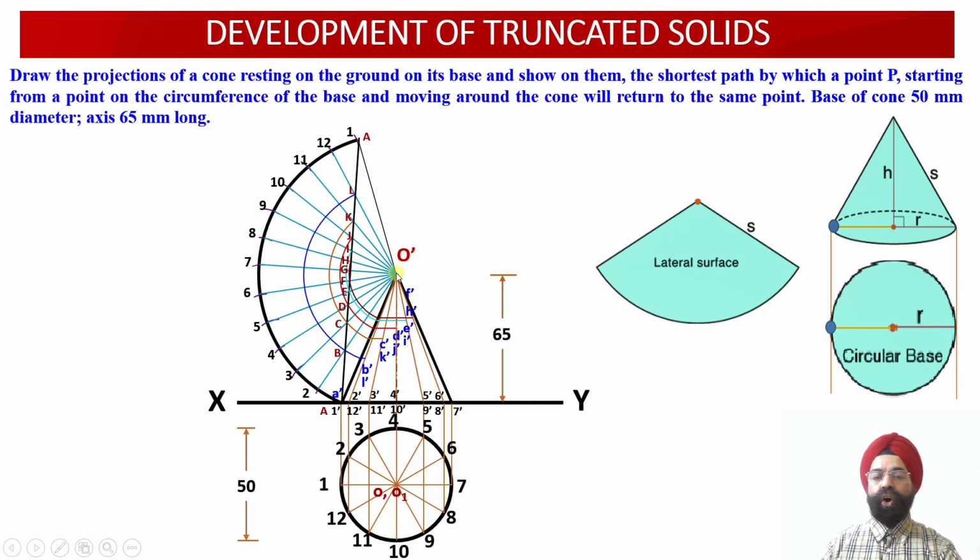So now onto O'7' in the development surface view, the point of intersection happens to be G. So through point G, once again we have drawn a curve, extended it up to the true length. From one true length O'1', we have drawn a horizontal projector up to the another true length O'7' over here. So this point of intersection of this horizontal projector will be G'.